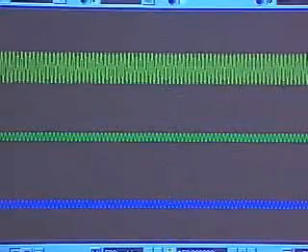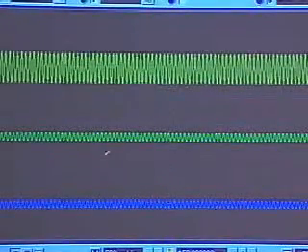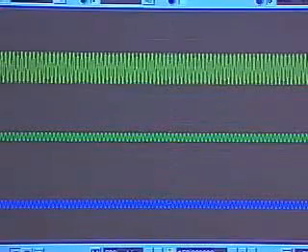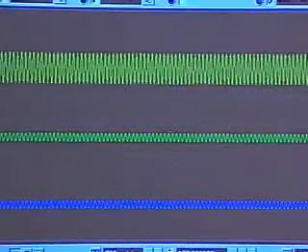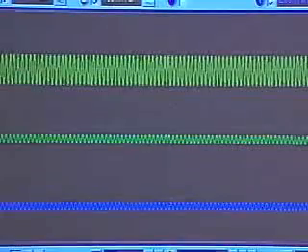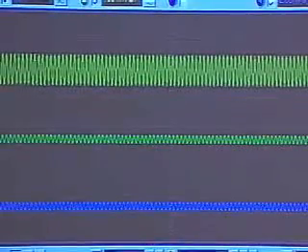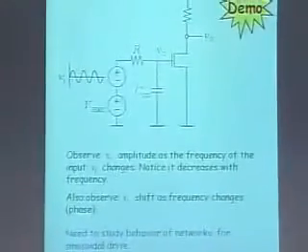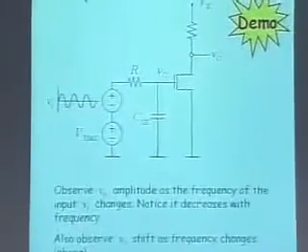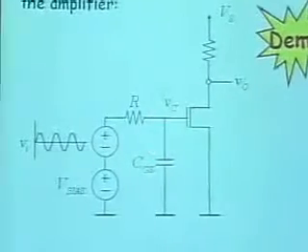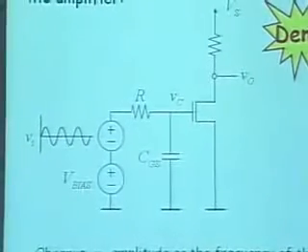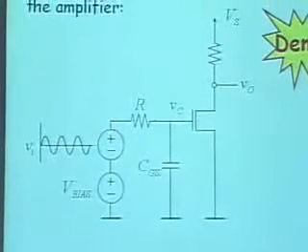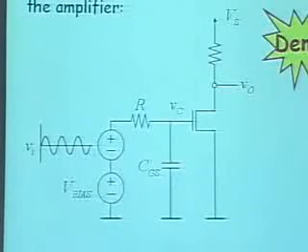Okay? And notice that this amplitude became smaller because the amplitude of the green became smaller. And remember, the green was the voltage across the capacitor. So this is your RC, and here's my input. My input has the amplitude, which I'm holding more or less constant. And notice that VC has decreased in value as I increase my frequency. Just hold that thought.